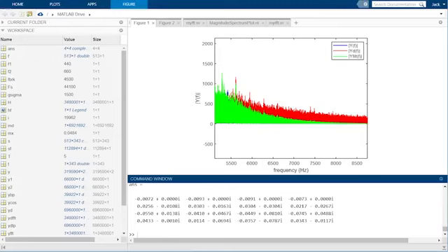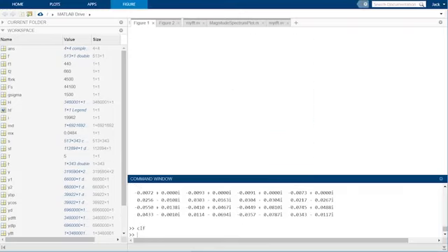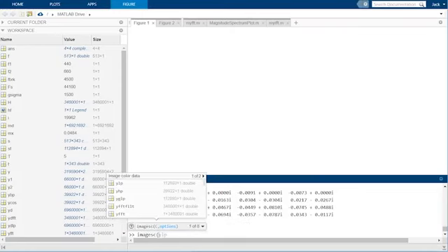So what's a better way to display the results? We can't display them the same way we did with our magnitude spectrum plots. There we had a single spectrum. Here we have 343. So plotting them the same way would make interpretation impossible. But 2D data we can display as an image. So, to display the result, we'll use the imagesc function, which can display an image in a figure window.